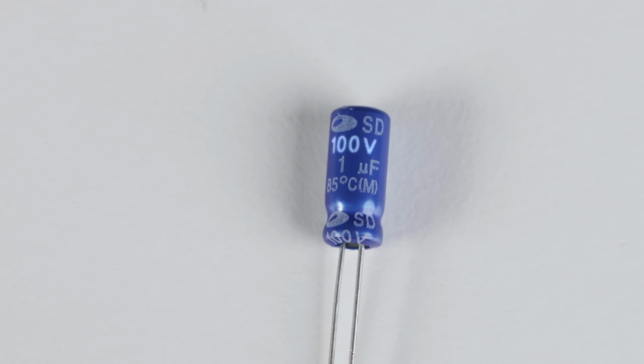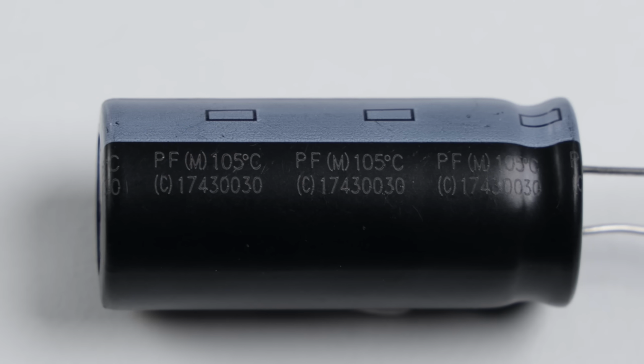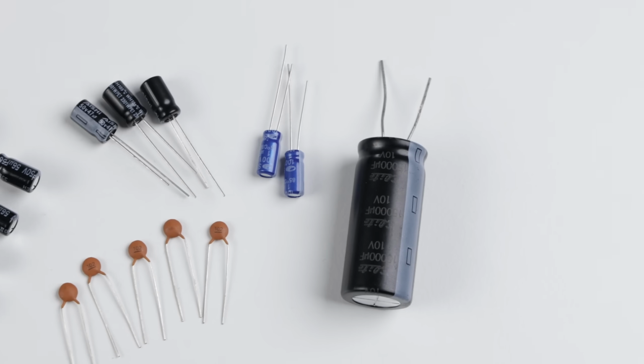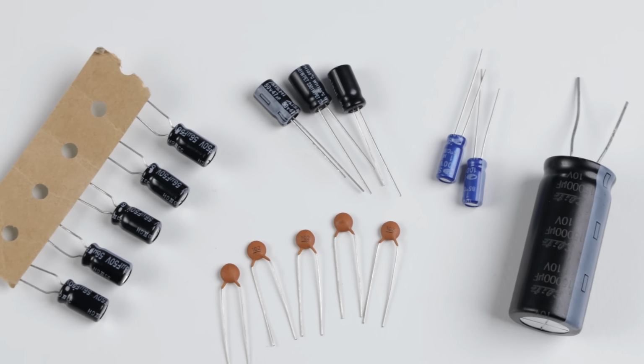Then there is operating voltage, the maximum voltage the capacitor can handle. The rule of thumb here is that the replacement's voltage should be equal or higher than the original one, never lower. There are also parameters like operating temperature range and case size, the physical size and dimensions of the part. For instance, the SMD packages like the 0402 or the 0603 are standardized, and selecting the wrong size can literally make the components not fit to the board. Make sure to check if it is in inches or in millimeters.